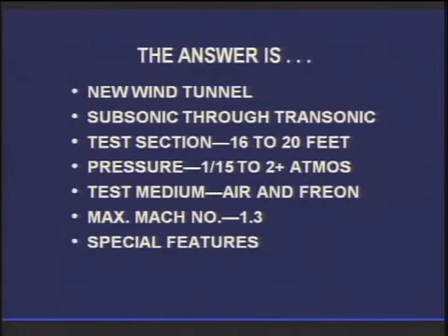Aeroelastic testing is a risky business. Models can be easily damaged, blow down the tunnel. So you need some means of stopping the tunnel quickly when one of these things occurs. So a flutter point is reached, slow the tunnel down so the model doesn't vibrate to destruction. But even though you can slow the tunnel down, it doesn't always work. Sometimes the debris goes down the tunnel, so you need a lot of protection for your fan, something that's not ordinarily in most wind tunnels.